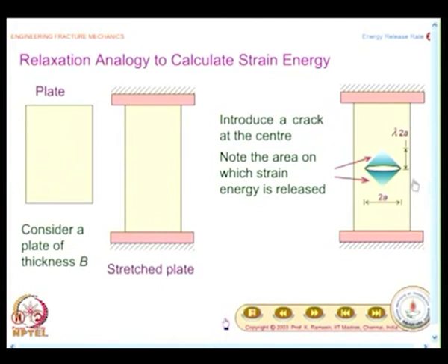Here again, for the crack to propagate, I should have introduced the crack, and after some length the crack would have propagated by itself from the strain energy of the system. And if you visualize it that way, this example is not complete by itself. Here again we are bringing in a thought experiment. The sheet was stretched and suddenly a crack opens up and you calculate the energy.